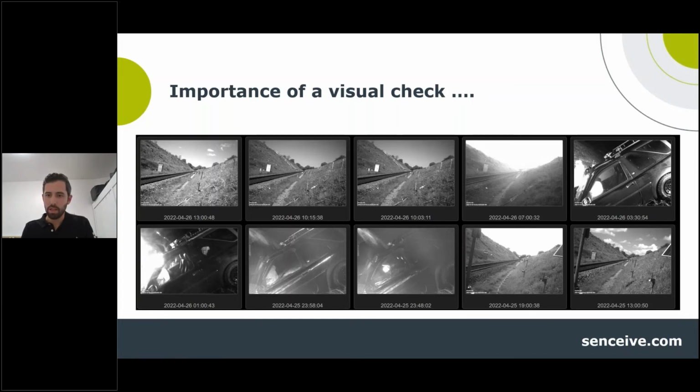Right now we're looking at a time-lapse showing a 1 p.m. shot, then moving clockwise from the bottom right-hand side to the next photo, a 7 p.m. time-lapse shot showing all clear. And then right before midnight, we see a Land Cruiser came off of the slope above the roadway and really just drove right through some of these nodes and then triggered all these actions to happen. So increased sampling rate, photos to be taken. You can see 11:48, 02 seconds, there's a photo, 04 seconds, there's a confirmation photo. About a minute later, there's another photo.